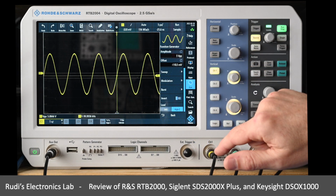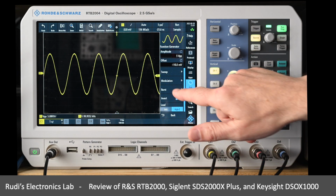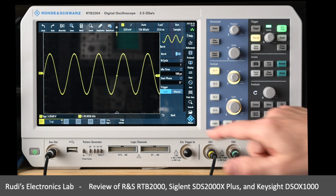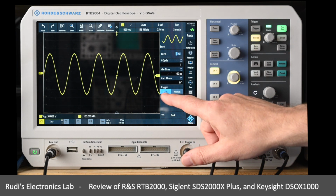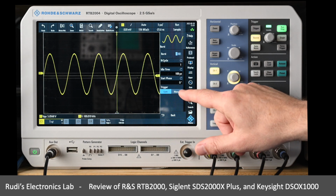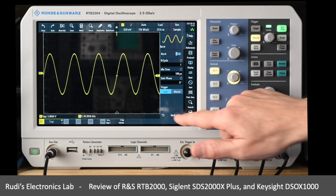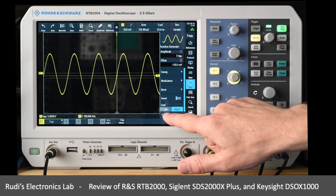We got modulation, I'll turn to that in a second. We got burst here, so we can decide how many bursts of a particular waveform we're going to see. And then we're going to get some silence, and we can trigger them again after the silence, or we can have a manual trigger actually coming in from the trigger input of the device. So fairly a lot of flexibility here.